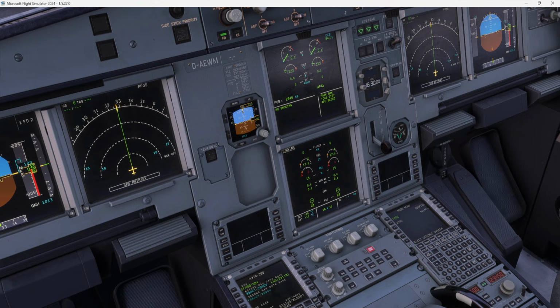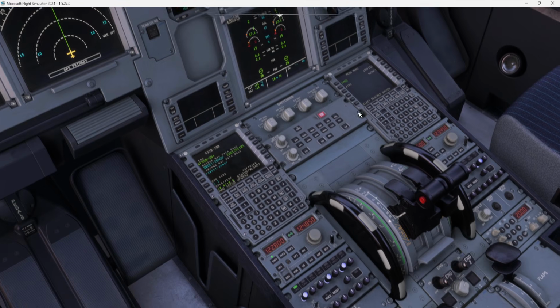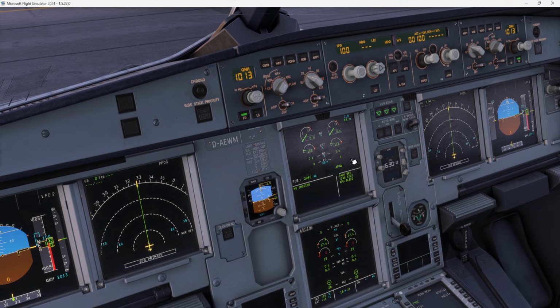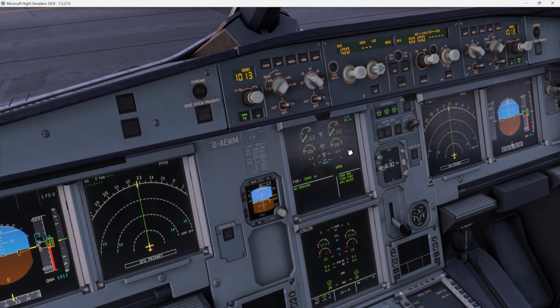So the engine is going to start running. Which one is going to start first? The N2, guys, not the N1. Once I turn this on, the N2 is going to start rising. It has a percentage. The N2 is the high pressure system, which is the high pressure compressor and high pressure turbine, and it is going to start rising up to 22.